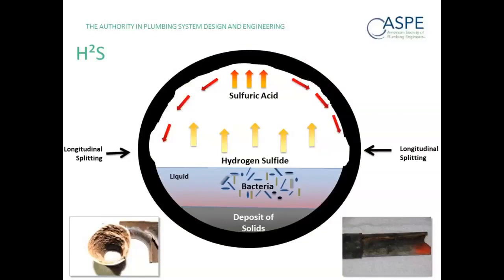Well, that is lighter than air, so what that does is it comes to the crown of your pipe, condenses and forms sulfuric acid, which on that vertical pipe, because the vent pipe kind of tilts back in towards the waste system, resulted in a constant trickle of sulfuric acid running down the piping system. So this is corrosion that's caused by hydrogen sulfide. It's not just an odor problem, it's a physical problem to your piping systems. Very, very prevalent in the municipal systems in Vegas, for example. Go ahead and advance, Jimmy.